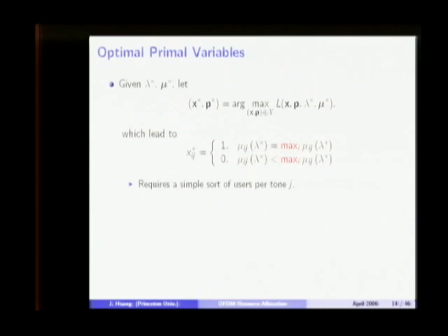Well, yeah, in the single user case, and presumably in a multi-user case where the powers are tightly constrained, where channels that are bad for everybody go unused. So all the xij's for that channel for all users might be zero. Right. So precisely, here when this term achieves the maximum, any value between 0 and 1 would be dual optimal. So in the single user case, unlike the multiple user case, when there are enough users, there's always one user who has a good channel quality at one particular carrier. So you want to allocate one user to that.